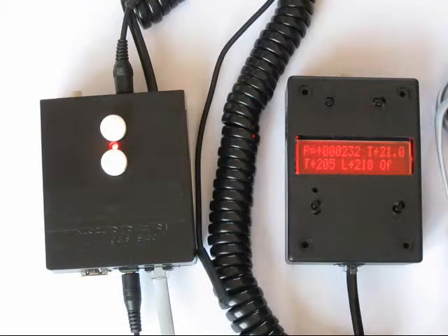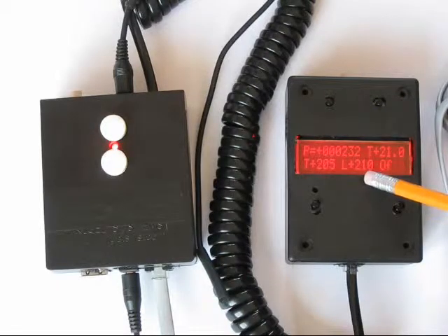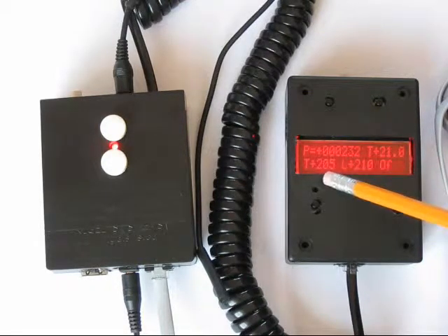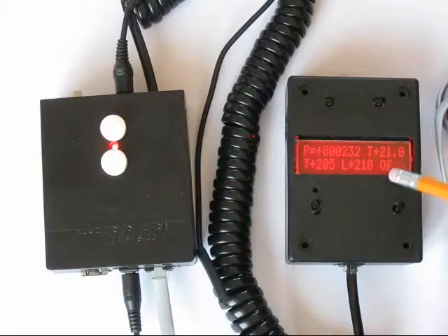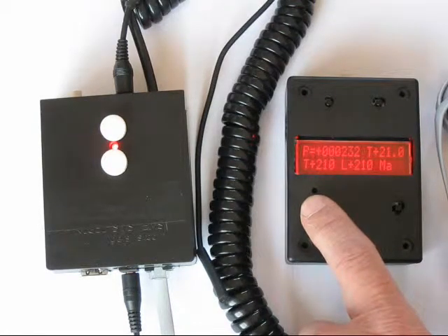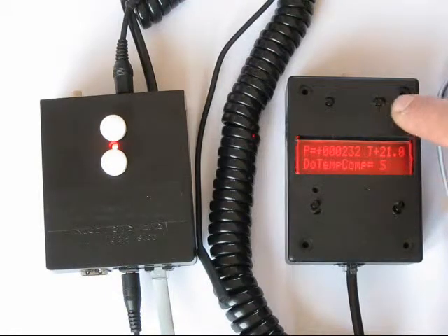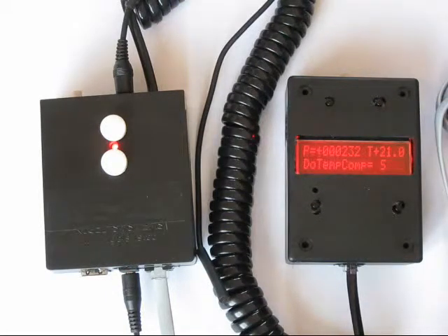And this is the main menu for temperature compensation. It shows you the last target temperature, the last temperature compensated at, and whether it's off, manual, or automatic. Right now it's set for off. If I walk up here to manual, this allows me the next submenu item, which is a forced temperature compensation.